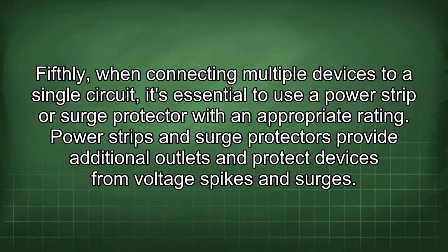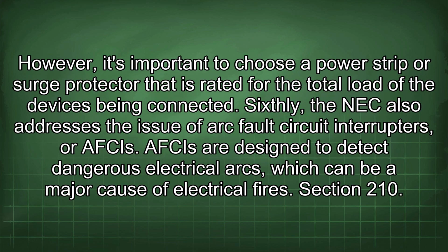Fifthly, when connecting multiple devices to a single circuit, it's essential to use a power strip or surge protector with an appropriate rating. Power strips and surge protectors provide additional outlets and protect devices from voltage spikes and surges. However, it's important to choose a power strip or surge protector that is rated for the total load of the devices being connected. Sixthly, the NEC also addresses the issue of arc fault circuit interrupters, or AFCIs.